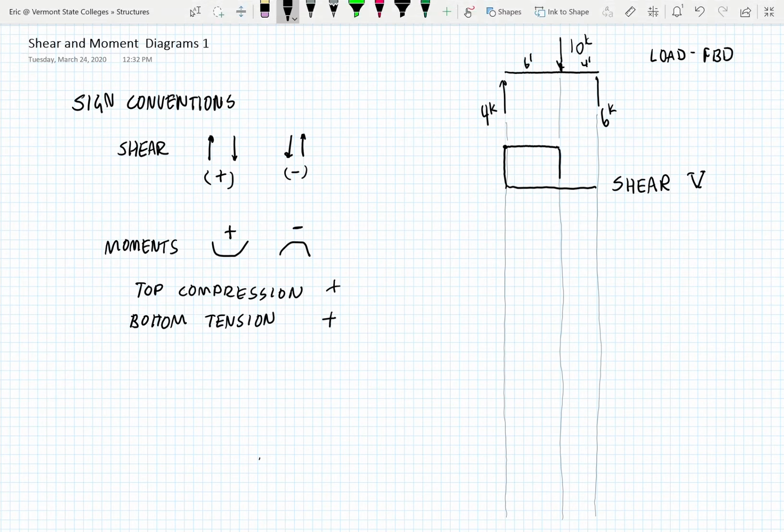So we're going to go down 4 and then 6 more. So this is 4 kips here, and this is minus 6 kips here, and the difference between 4 and minus 6 is 10. And we're going to go across. We have no change in load, so there's no change in shear till we come to this 6 kips, and it takes us back up to 0.